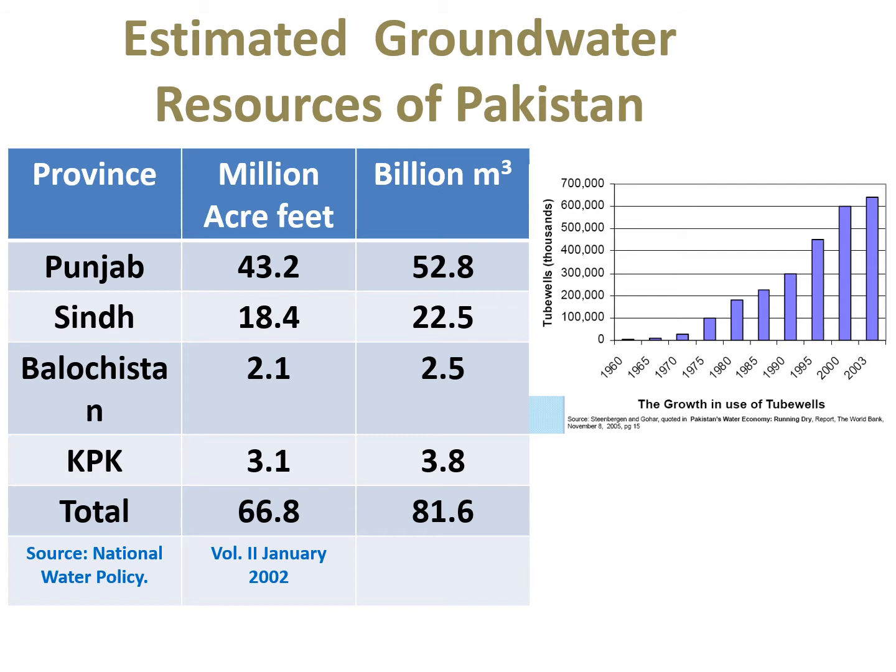It is totally dependent upon the soil profile and subsurface strata, what kind of situation there is underneath and what kind of available geological formation is there in the subsurface so that water can get stored and move, the most important. In KPK, water is mostly in the form of confined aquifers. It has a certain type of geological formation which is going to lock the water boundaries and create a confined environment.